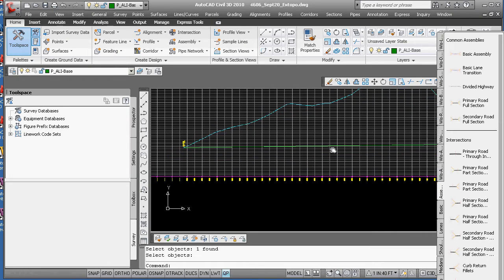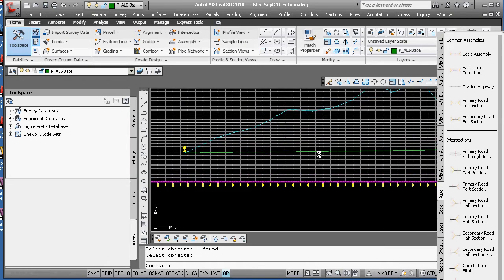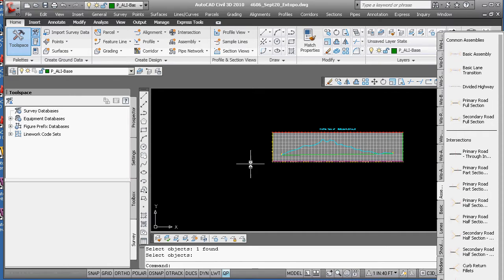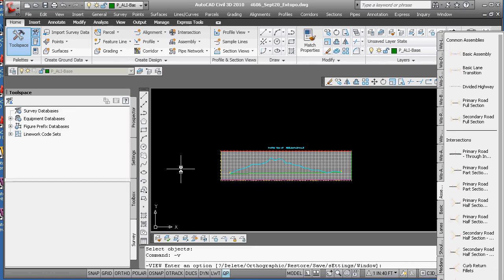I'm looking at now coming on to 10 minutes. You've got now an existing and proposed. The next step is to make sure you set a view. Minus V for view, W for window, overall, underscore profile. There's going to be a lot of different profiles in your drawing. You may give them names there. First corner from here to here, you now have two views.